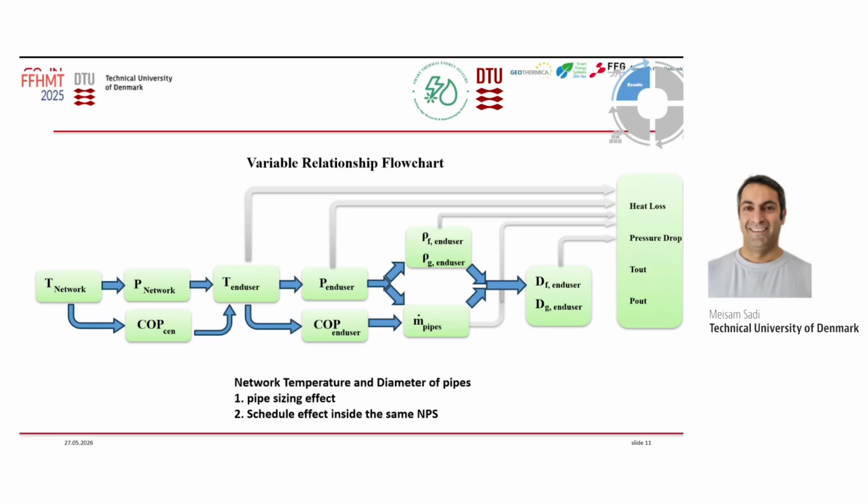When I say hydraulic design, I mean the pipe size and the schedule of the pipes, meaning the thickness of the pipes, which could introduce some discrete jumps in the calculation for the pipe size.